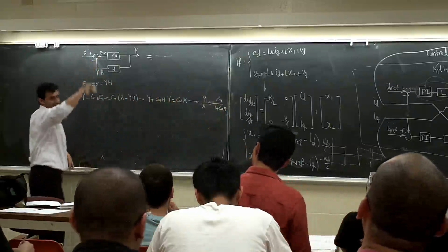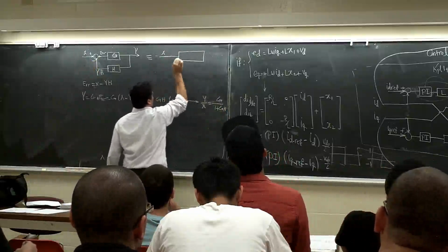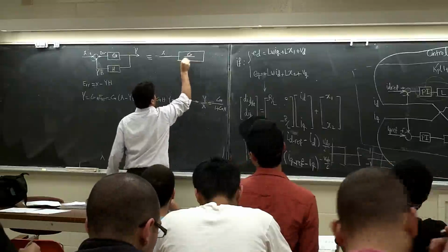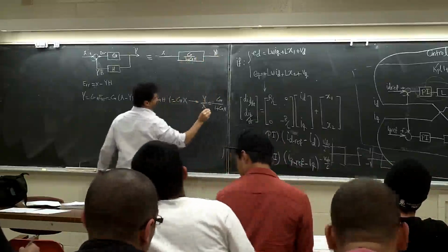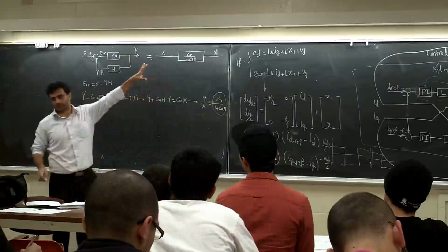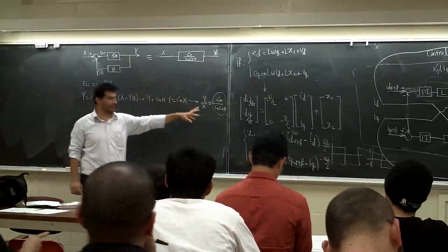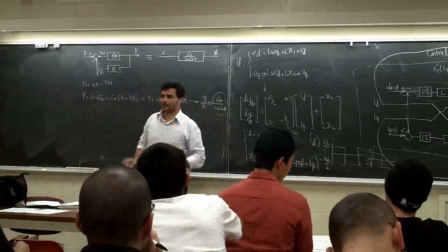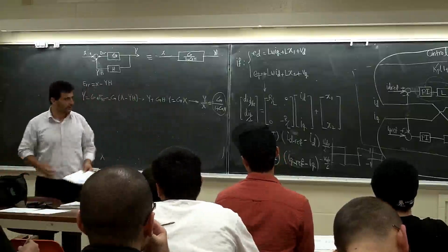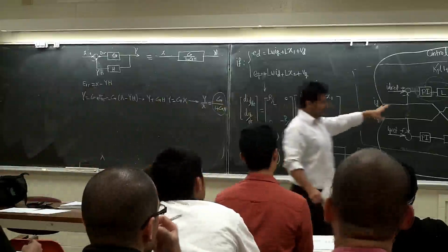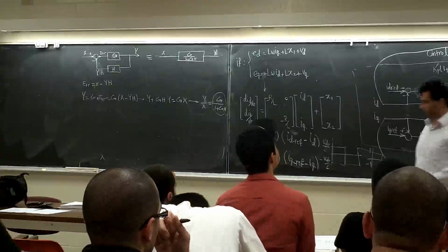Basically, instead of having a feedback system, you could have a system like this. X coming, going to this block, which is G over 1 plus GH, and this is a block, right? They call this one the transfer function of this system. They will use this transfer function for control analysis, for stability analysis. This is what they use. Now let's see what we are going to have here. I'm going to go back to this block diagram and do it for the D-axis. Q-axis is going to be exactly like D-axis, no difference.